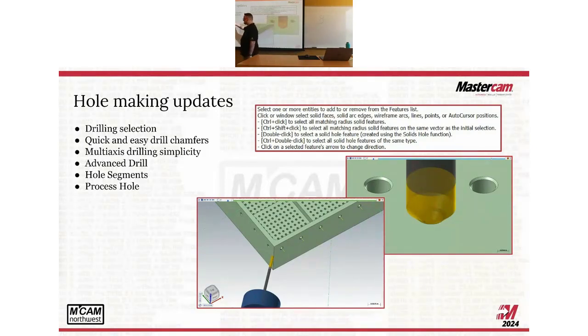We don't have time to go over these today, but I will say that advanced drill has a place on this part, and we'll see it later, where we've got like a 1/8 inch hole, but it has to go more than 2 inches deep. It's pretty far for a drill that size. And if you wanted a cycle where you take your short drill and maybe cut the first 3XD, 5XD, then you want to follow that with a longer drill. You start at a low RPM, guide the drill into the hole before you turn it up, because otherwise you get drill whip, right? Which I am still looking for a really good video on that. If anyone has a great video on drill whip, please send it to me. I want to see it.